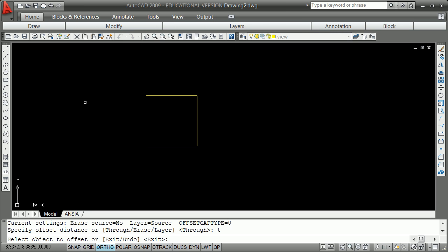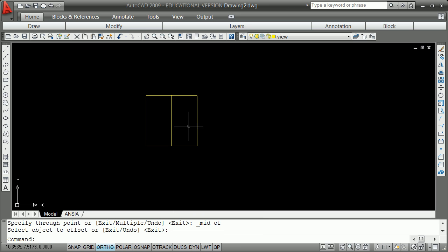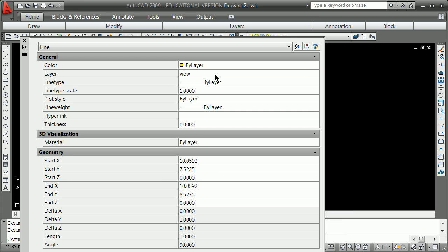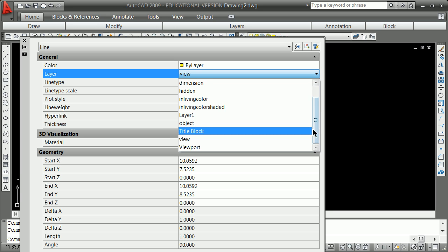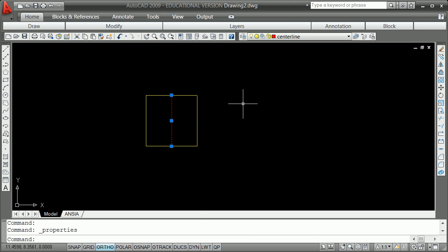We're going to figure out the center of that box, which we know would be 0.5, but since we've got something on that page, we're going to go to the midpoint. And just to be good, I'm going to left click, right click, and then change the property of that to center line. We're going to use the magic finger later, but learning how to left click on something, right click, and pull out properties is there. Now we're going to actually draft, and to review, we're also going to type LT scale, and then change the scale to something on the order of 10 up or down, so it's 0.1.